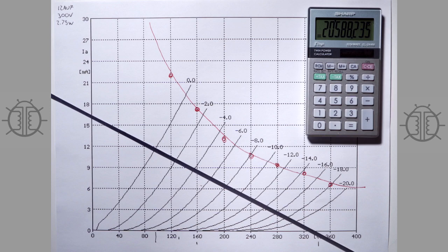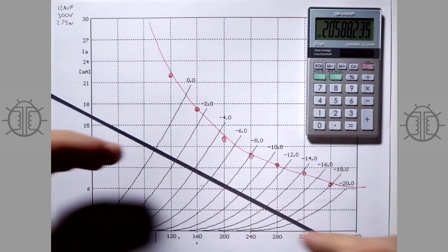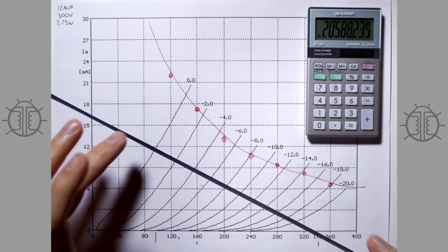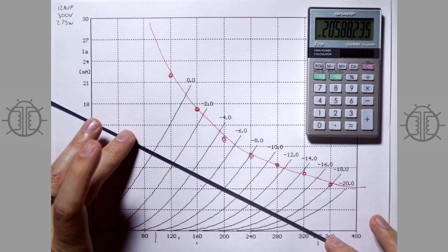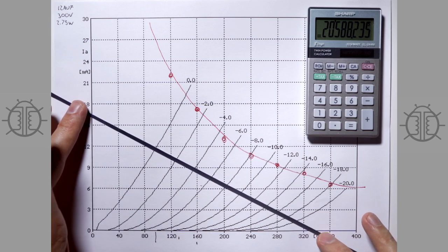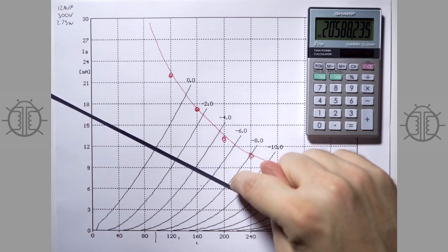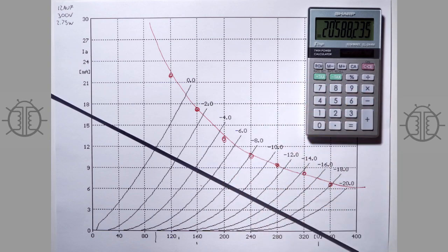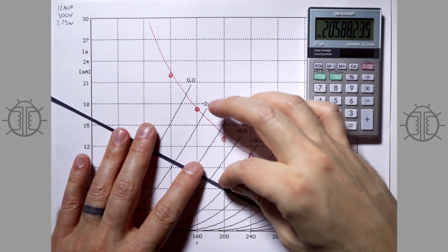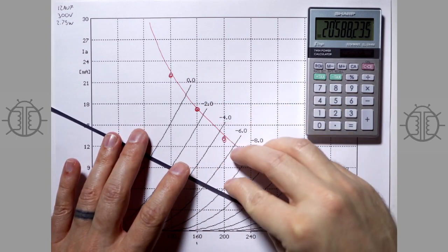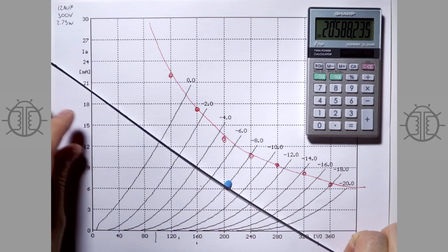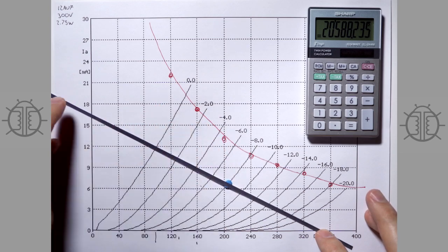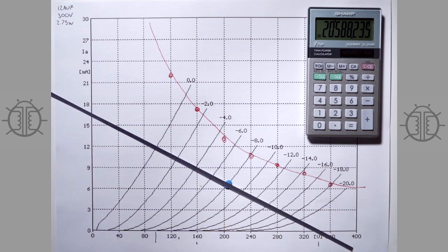So anyway, let's pick a DC operating point. It can be anywhere in here, but generally speaking, for maximum output swing, you would pick half supply voltage or whatever, or you'd pick halfway in between. So let's just say 350 and right here again, and so somewhere in the middle where you could go up 1, 2, 3, 4, and you could go down 1, 2, 3, 4, something like that. And so you're looking at an operating point. I'm going to put our operating point right here, and you'll see why I'll do that in a minute. There's our operating point. So it's 350 up to and 17 milliamps there.